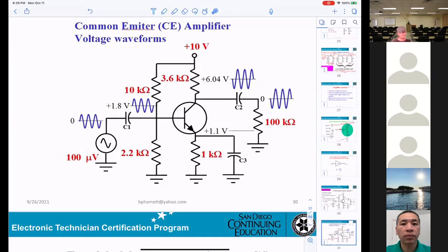If you set DC coupling, you can see the DC is too big and the AC will be too small, so you cannot see the AC like they show you here. The AC is very, very small, you cannot measure it. So that's why you must set AC coupling to block the 1.8 volt DC, and they display only the AC that you're able to measure.